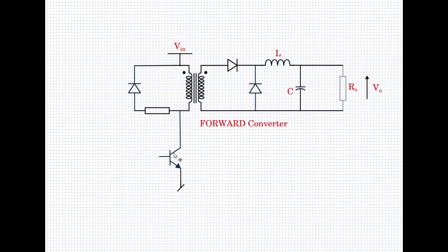When the switch is off, at that point there is a reversal of polarity here. Here the inductor is freewheeling and the primary side here will freewheel in this fashion and thereby reset the core flux. So this path is very important. Without this path, this transformer isolated forward converter will not work. So this freewheeling path is a very crucial path.